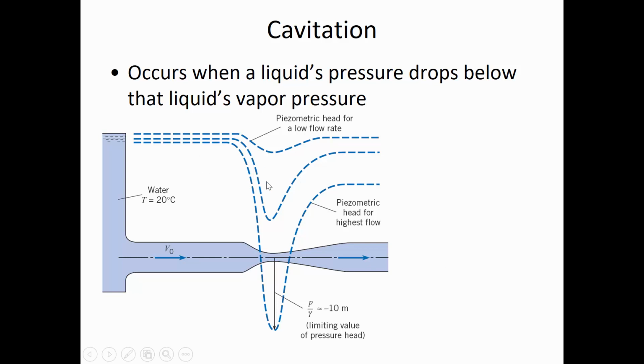Now we've drawn the dashed line here kind of to scale, in a sense. And the scale that we're using is that when that dashed line goes below the actual water surface, that is when we say that we have a negative gauge pressure. That actually the pressure is lower than atmospheric. Because, you know, as we go down in this reservoir, the pressure is increasing according to the unit weight. And so there's some positive pressure associated with our depth.